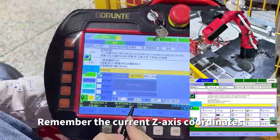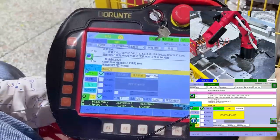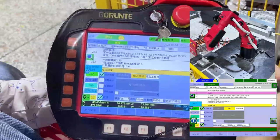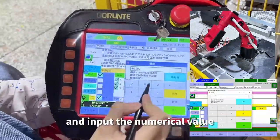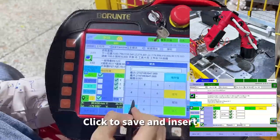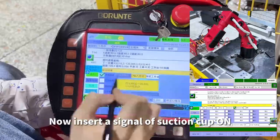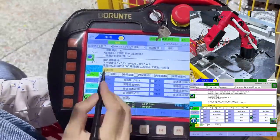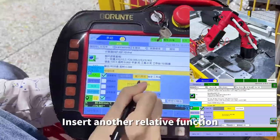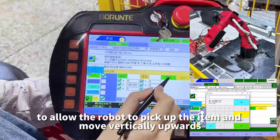Remember the current Z-axis coordinates. Then move the robot to the workpiece. Calculate the distance between the 2 points, and input the numerical value. Click to save, then insert. Now insert a signal for the suction cup on. Insert another relative function to allow the robot to pick up the item and move vertically upwards.